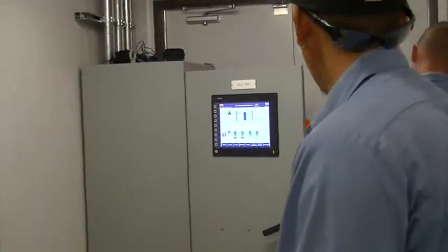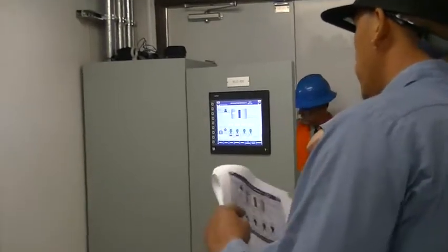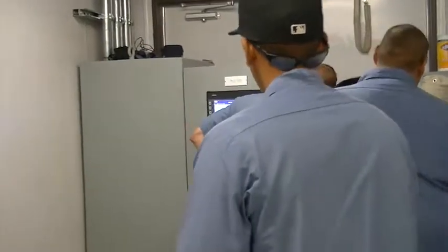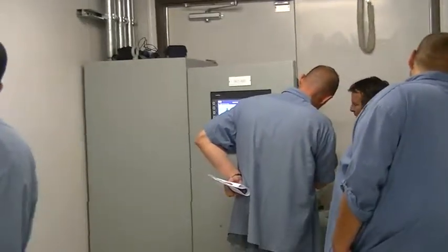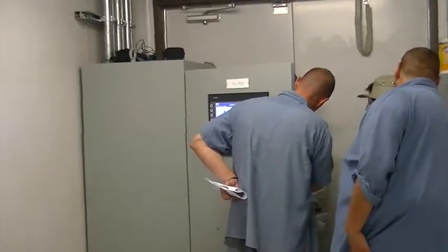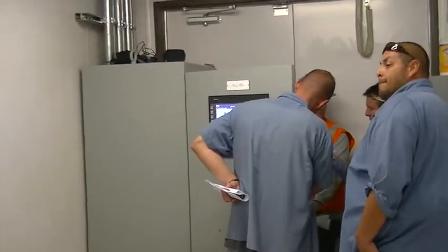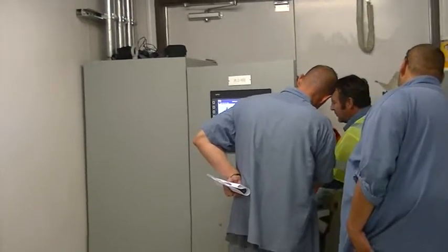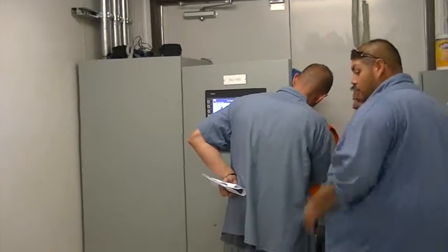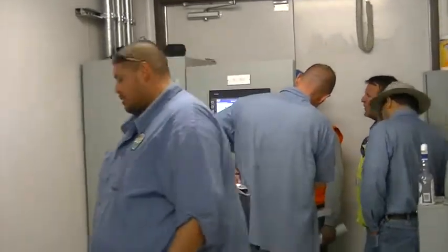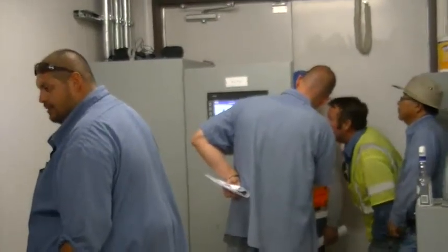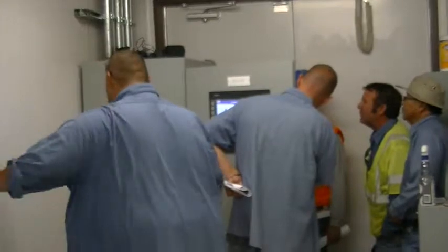The other thing back here that I need to show you is for the UPSs, we have that switch, which is in normal. If you want to bypass the UPS, you flip it over to bypass, and it will take the UPS out. Like if your battery backup fails, you can change it over to unplug it and replace it, because I've had to do that over there. Yep. There's an intrusion alarm on this, so that controls the light and the intrusion alarm.